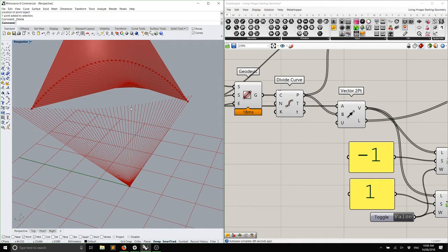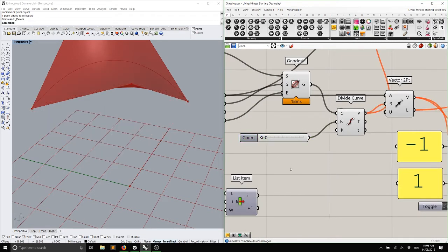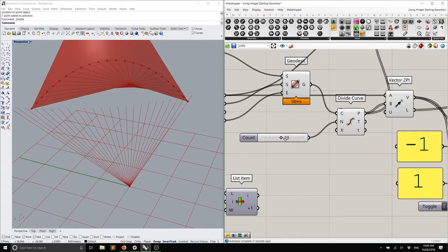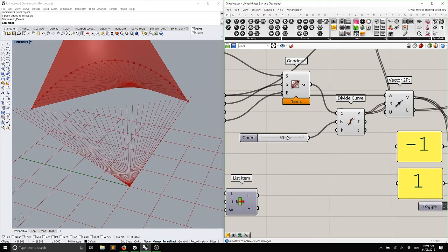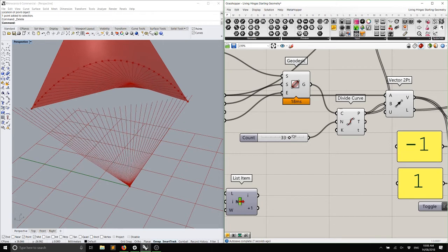So how did you change the amount of lines there? I right-clicked N, set integer, and then typed 50 in. But you can also use a slider. So yeah, we could say 0 to 50. Right-click N. Yep. That's my habit of just using fixed values. You can also put a slider into that.